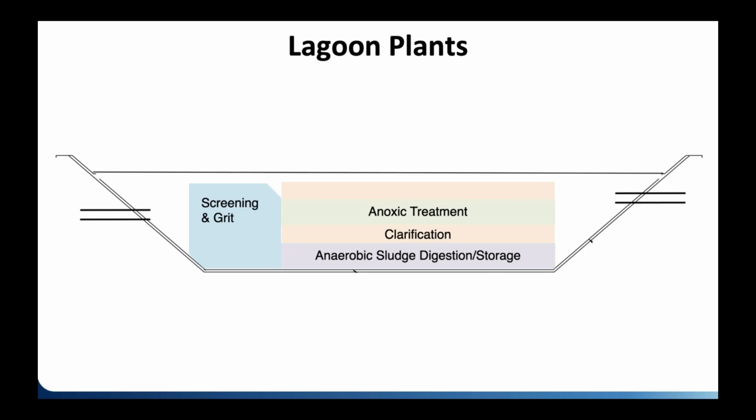Then you have an anoxic zone, and finally an aerobic zone at the top. And that's where you've got wind action coming down, mixing water, adding oxygen to water, and so on. And let's not forget about disinfection. Because lagoons are so big and have such a big surface area due to their size, these UV rays from the sun actually disinfect the lagoon water.